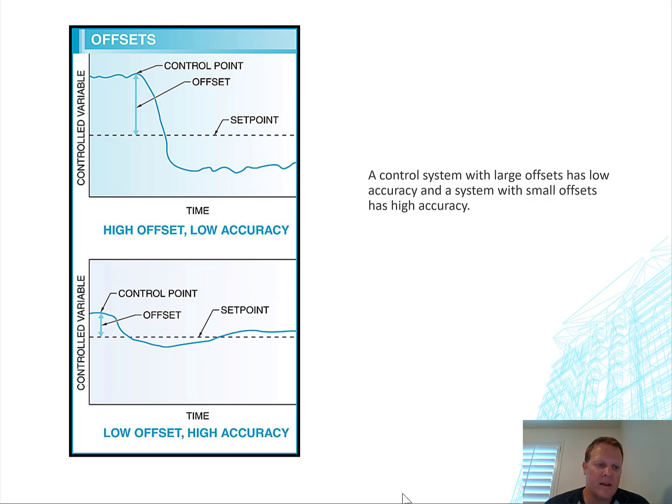And I think the point of this was mostly to say, hey, we could have a large variable of how much it's being controlled. For instance, humidity control is maybe not super controlled inside of a home, like on or off. It might say, hey, we need some humidity, let's go ahead and turn it on. But man, it's so far from where the set point really wants it to be that it shuts off. But then it kind of gets back to a point where, oh no, we need to turn back on.